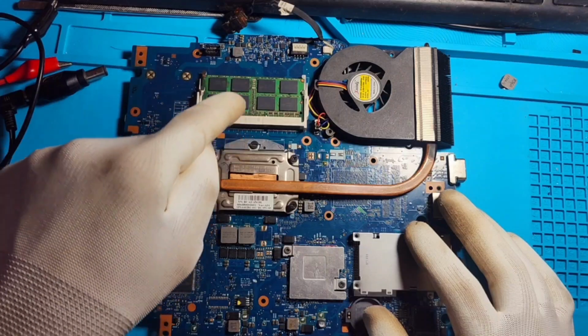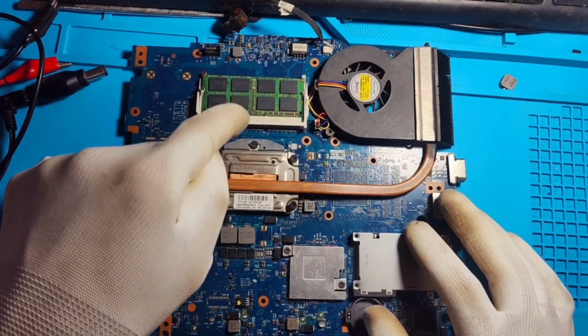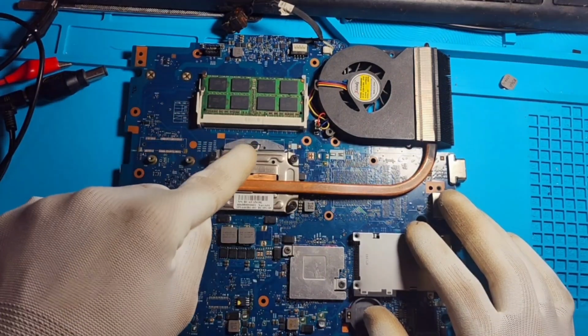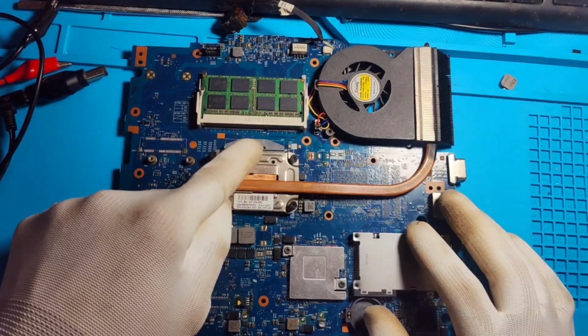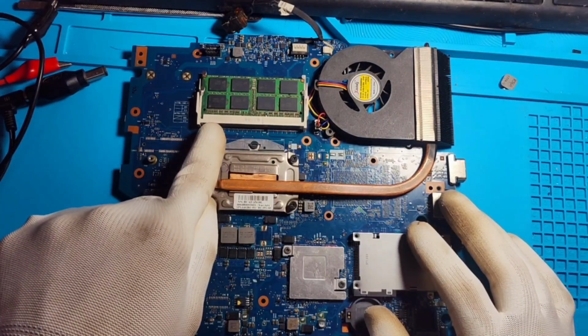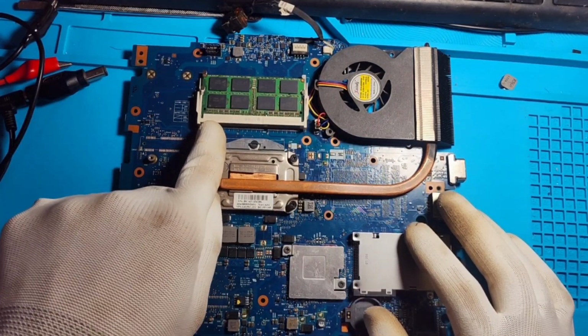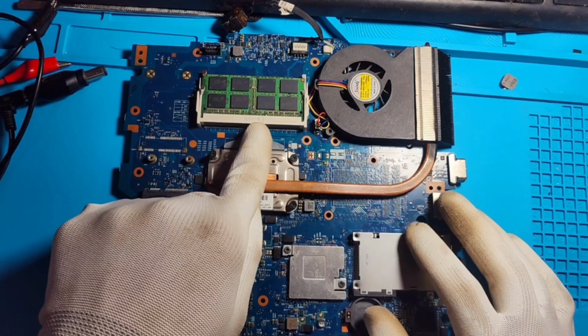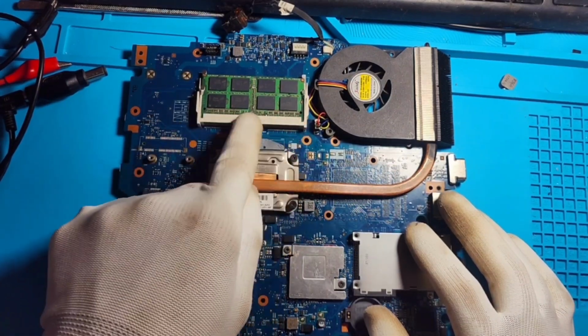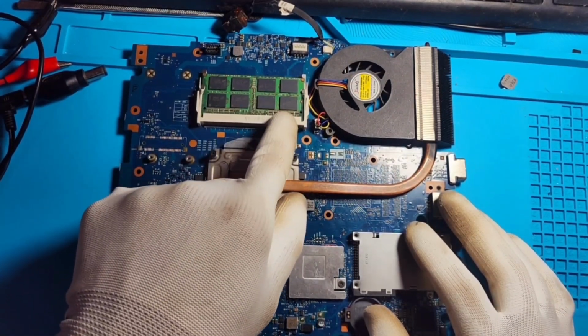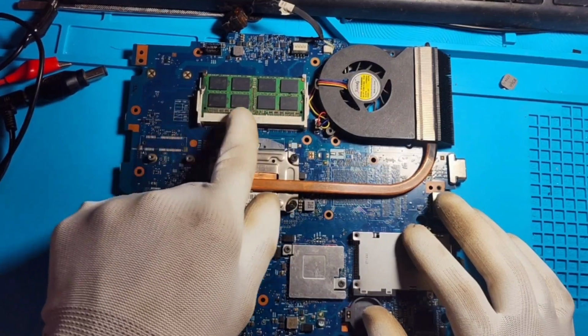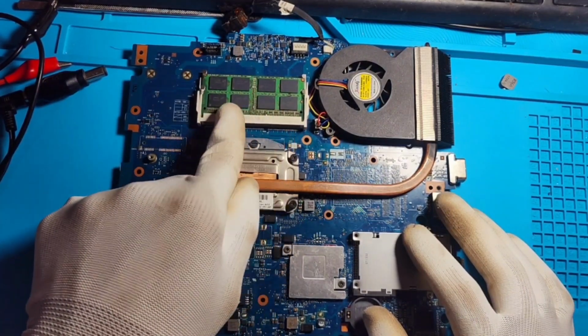The voltage for the network connection is known as VTT, which is half of the RAM supply voltage. In this case the supply is 1.5 volts, so we should get 0.75 volts as the VTT voltage here. We need to check that voltage also in order to find any problem with the RAM section.